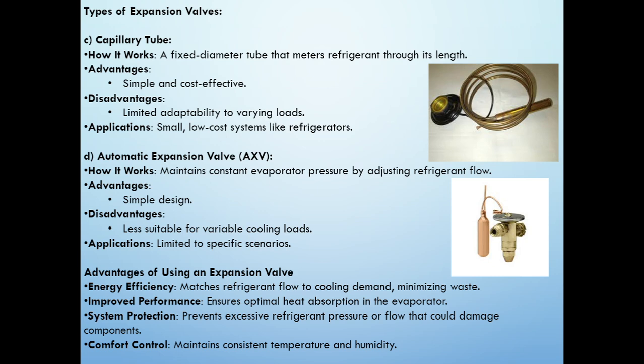Number four, automatic expansion valve, called AXV. As you see in this picture, it maintains constant evaporator pressure by adjusting refrigerant flow. The simple design is an advantage. Being less suitable for varying cooling loads is a disadvantage. It's limited to specific scenarios.